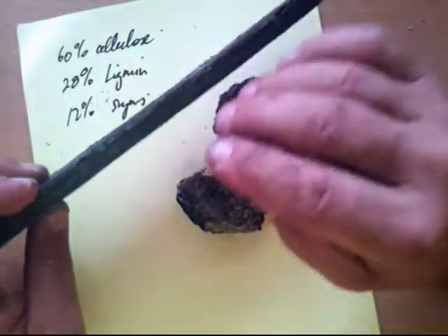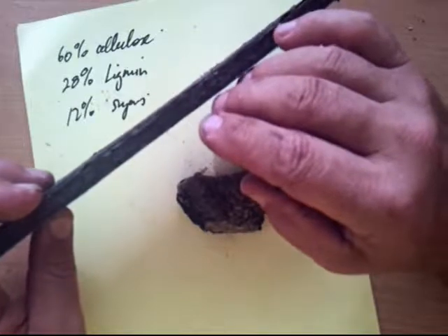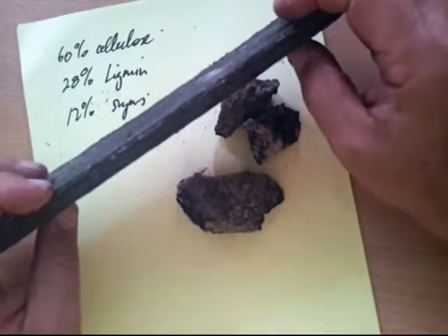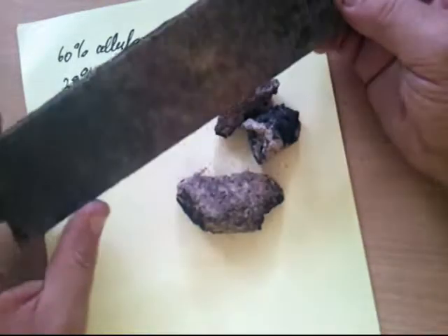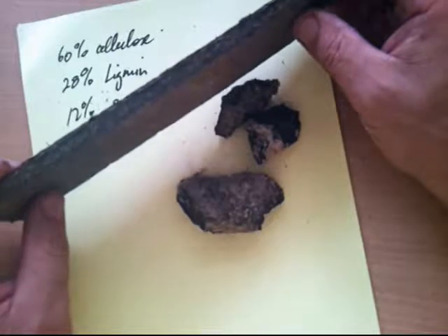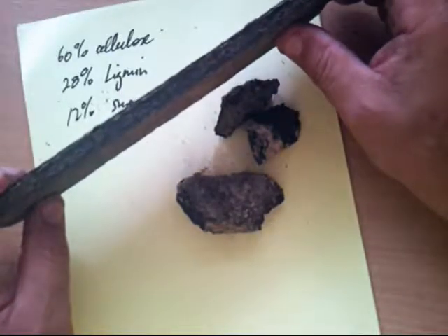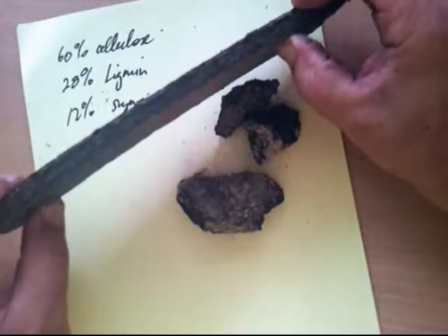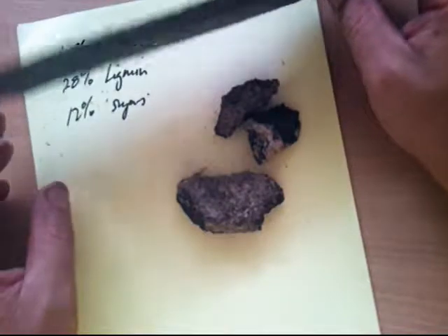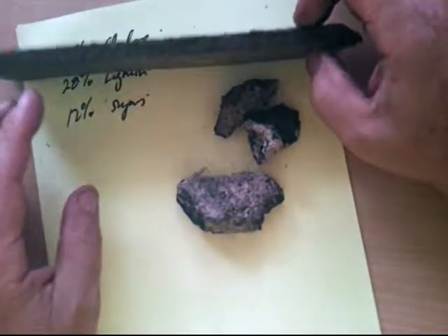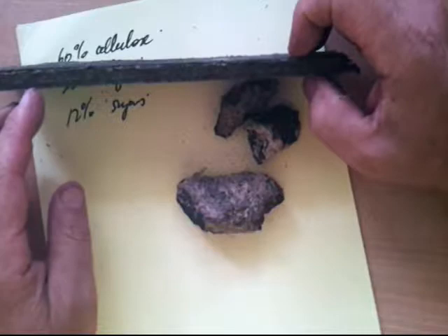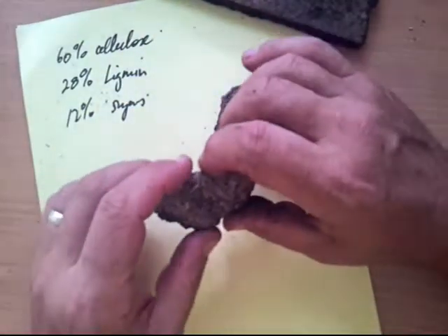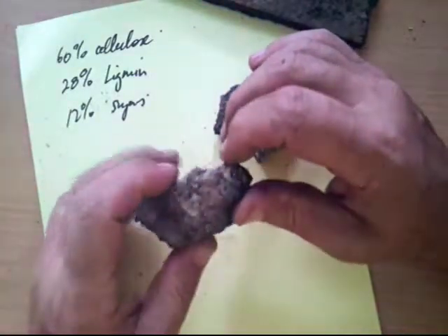Another use is impregnating. This is a fibre that's been impregnated with asphalt, and it's used as an expansion joint between concrete slabs. It stops the slabs from cracking by providing a weak area, a weakness where it allows a bit of movement, and this is an expansion joint, and it's been impregnated with tar or asphalt to make it useful. You want it to last and not break away. So its waterproofing qualities and flexibility are important because you've got to shape it into corners and fit it in. So that's another use of asphalt as a jointing in between concrete slabs.